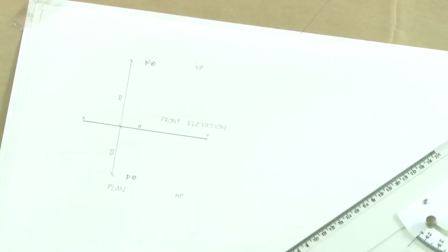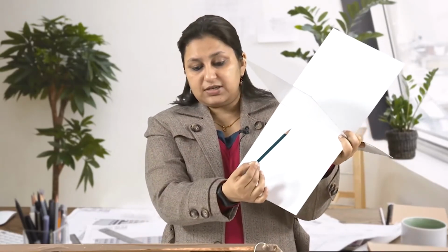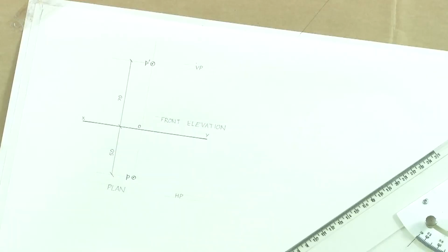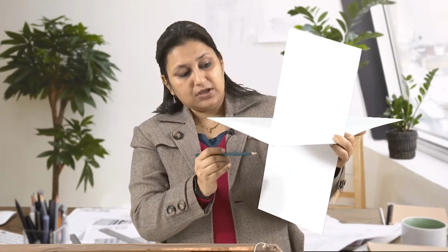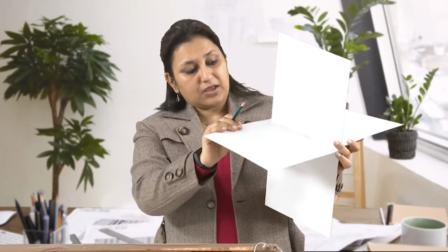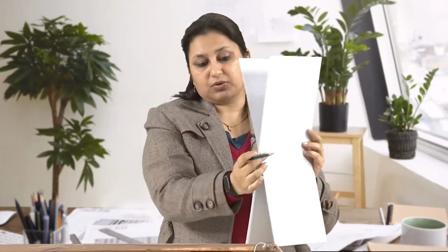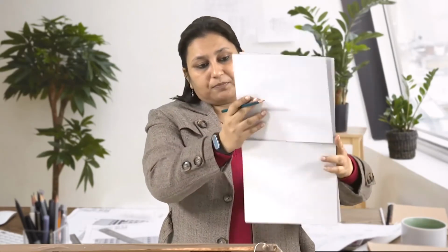Now, just imagine that the same point, instead of being in the first quadrant, was in the third quadrant. So, I am just flipping it over, but please keep in mind this is the first quadrant and this is third quadrant. So, what if I have a point here which is at 50 mm from HP, 50 mm from VP and 70 mm from HP. Now, what happens? The moment we have it like this, it is going to fold like that only. So, whatever we will be seeing in HP is going to go up.